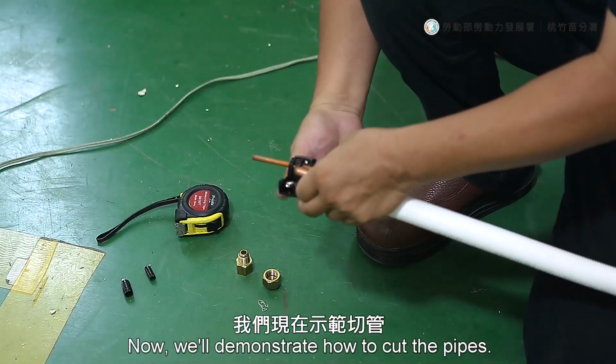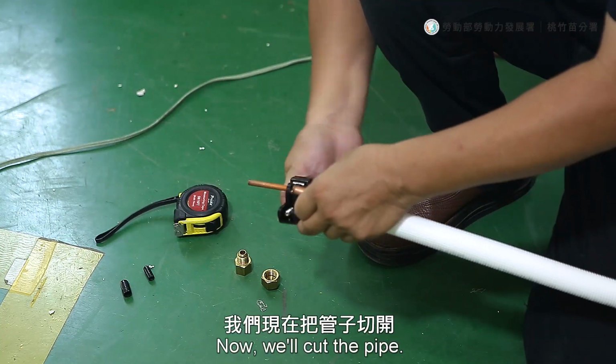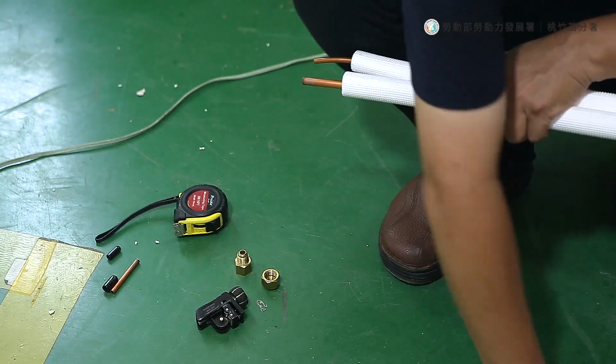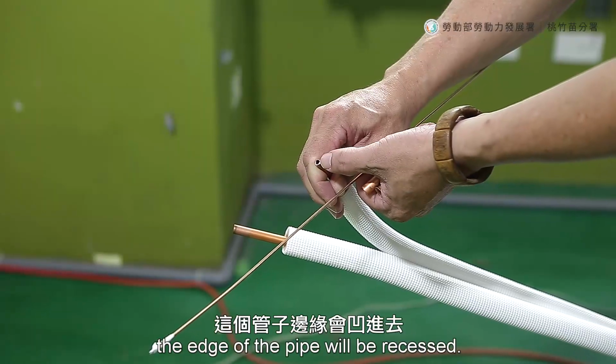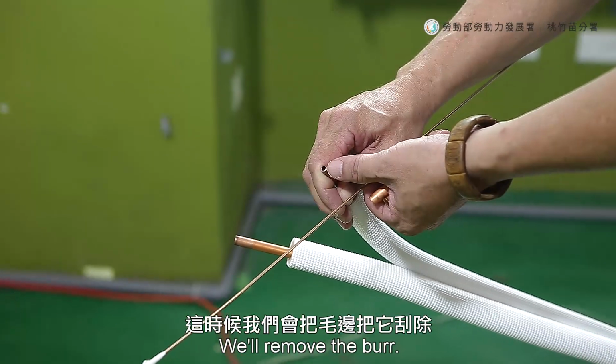Now we'll demonstrate how to cut the pipes. This is a pipe cutter. Now we'll cut the pipe. After cutting, the edge of the pipe will be recessed. We call this burr. We'll remove the burr.